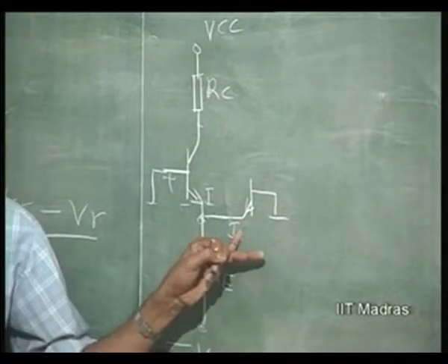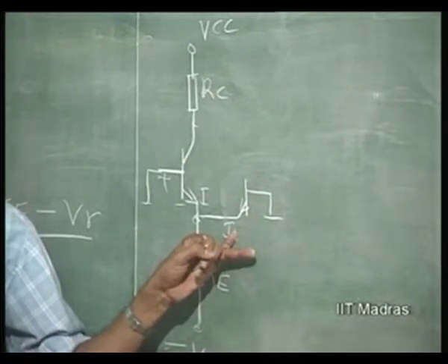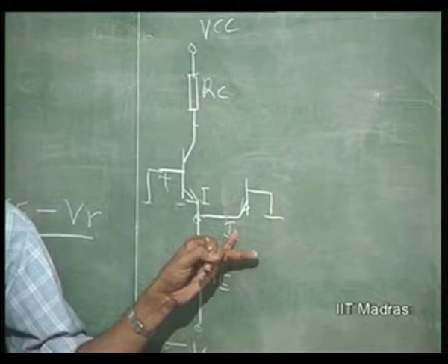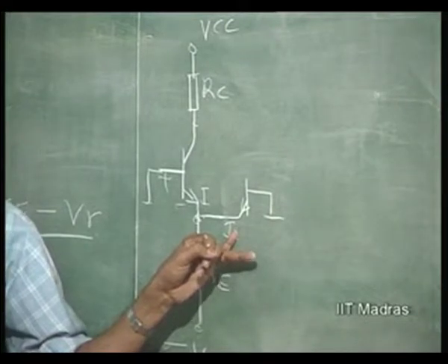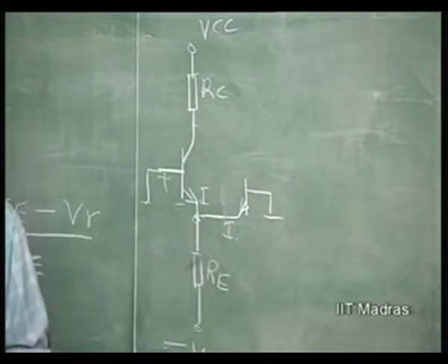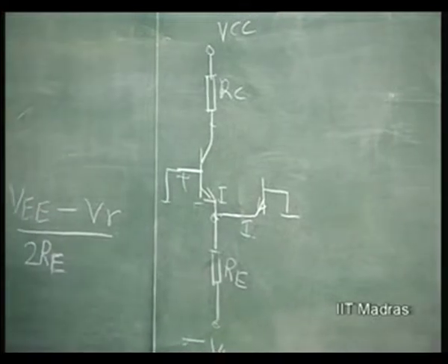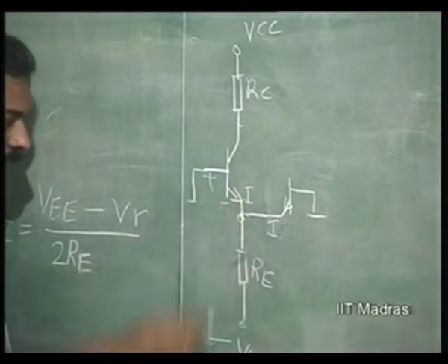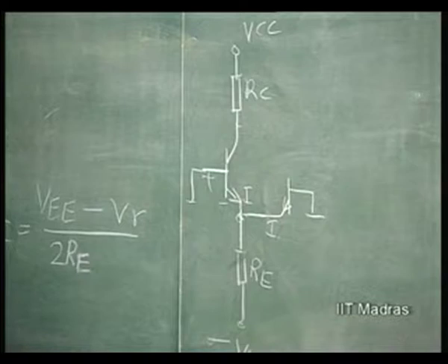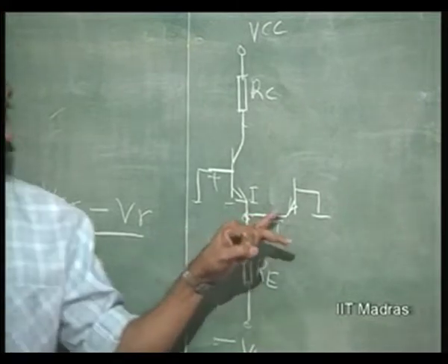This kind of design has become very popular in integrated circuits, exploiting identical characteristics for your design. So, these two are now operating at the same current, therefore the operating point is fixed. Now, what is the effective resistance from here to ground?